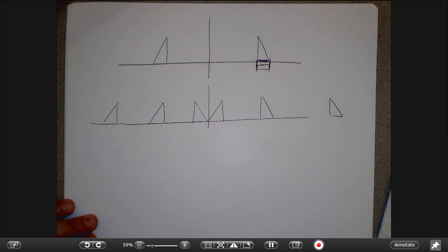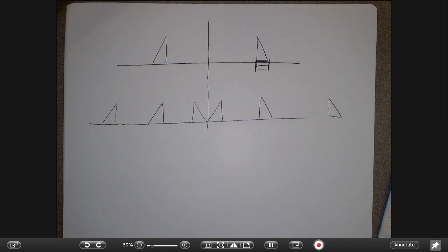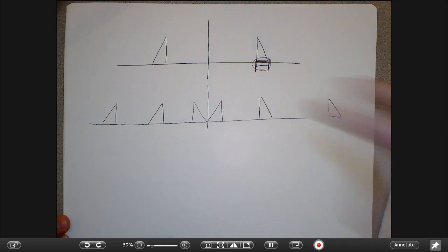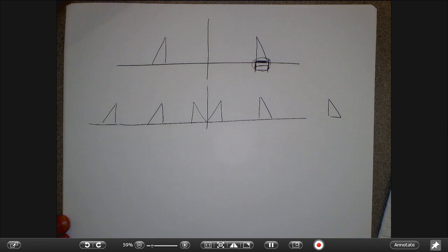And that intuition is correct. So you can get away with very low sampling rates as long as you know this a priori. You have to know that band. You can't just get away with knowing that the signal is 100 hertz wide somewhere in the frequency spectrum. You have to know exactly where that is to know where the copies are going to land. But it may be that you know exactly what your spectrum of interest is, and then that would work.